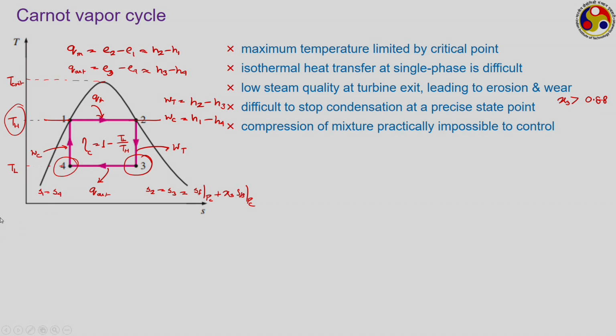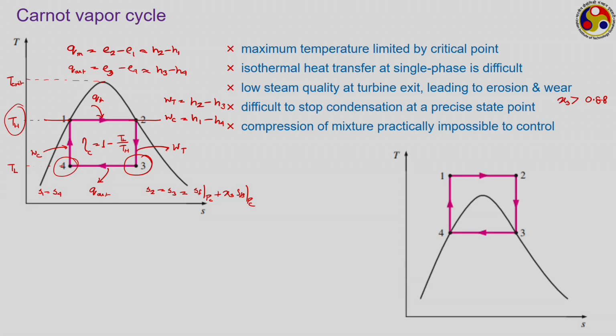One way we could have achieved this cycle is by shifting the entire thing towards a higher temperature limit, something like this, where we have phase change going on for the condensation, but there is no phase change in the boiling part. In the heat addition part, here we have heat addition in the supercritical stage. This particular temperature level is well above the critical temperature. So, we are somehow taking care of this particular limit, and the heat addition is taking place at supercritical level, though heat rejection is still within this phase change dome. There is still phase change involved with heat rejection.